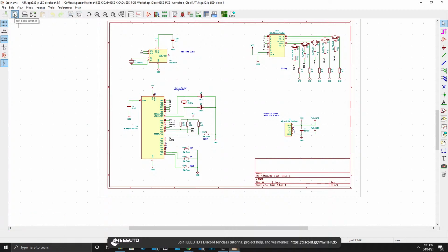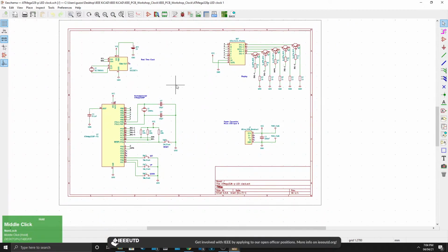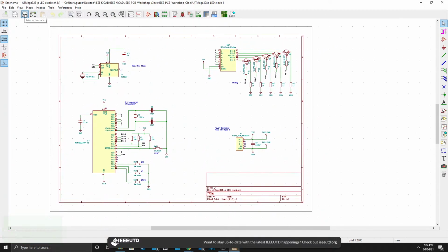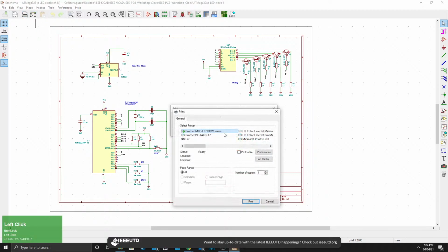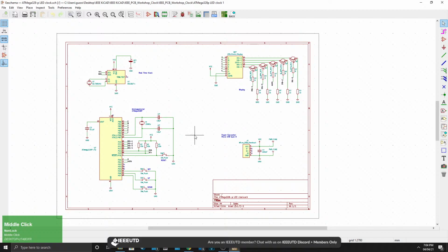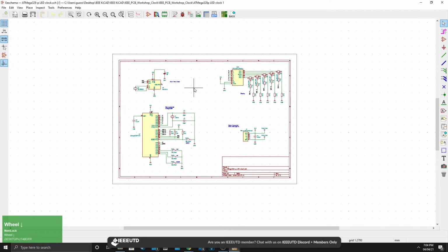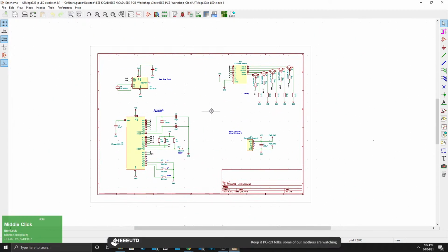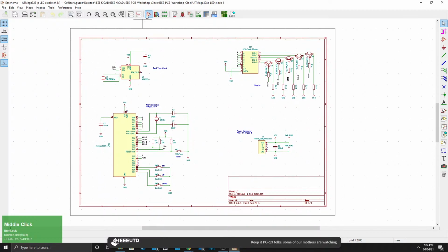You start at the left, you do the edit page settings. These aren't really part of that list that I'm referring to. It's just printing and zooming and things, which you don't usually touch other than printing out the schematic design as a PDF. If you're curious about how to do that, you would just click print and then choose to the right, print to PDF, and then you can print the design. That's how I printed the reference that is in the 0th project file for you to design the schematic. So you skip these, and obviously the navigate schematic hierarchy, which I talked about.